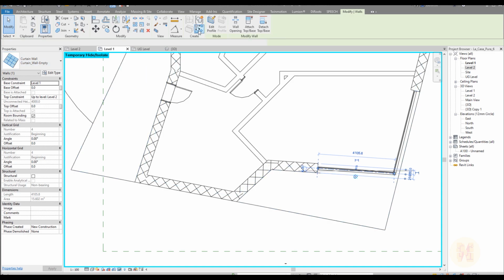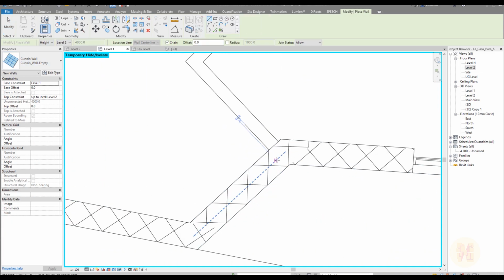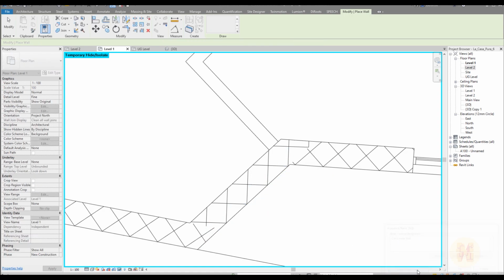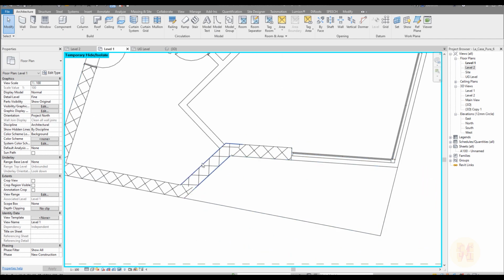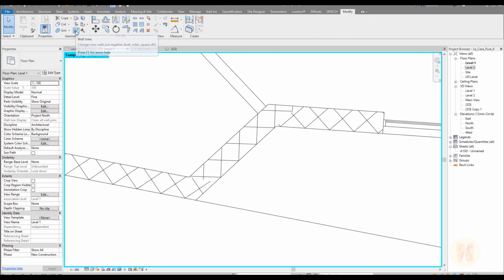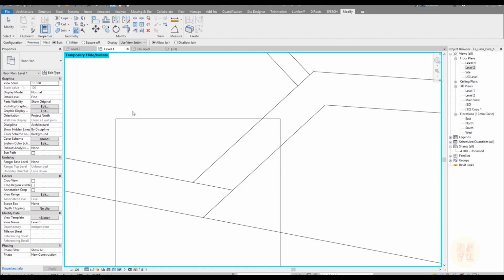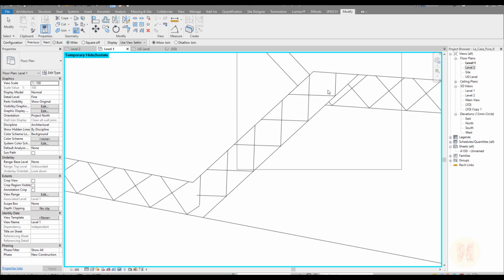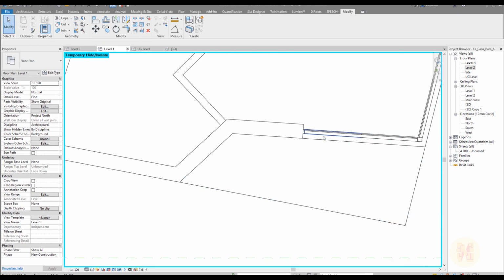Let's use create similar, and let's place it exactly on this side, from this side to this one. Here it's really hard to understand where I should place it. Delete element, delete element. So this one, it's really hard to understand where you can place it. First, before we place it, let's go to modify, here the connect wall joints, and let's change the wall joints by miter, and as you can see, it's cutting this way, and here we'll do the same thing. So now we can exactly place our